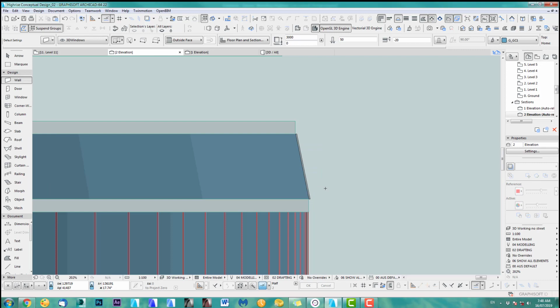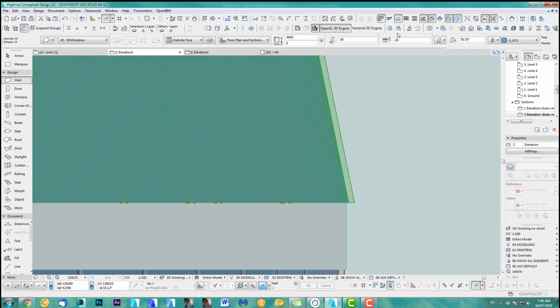All right, that's much better. And now you have to obviously select this. I'm grouped, and this is just the offset of the wall. So if I do 0, let's see where it goes. There we go. We got 50 thickness. Let's do minus 50 then. Or hang on, 50 first. I think it's going, yeah, it's going this way.